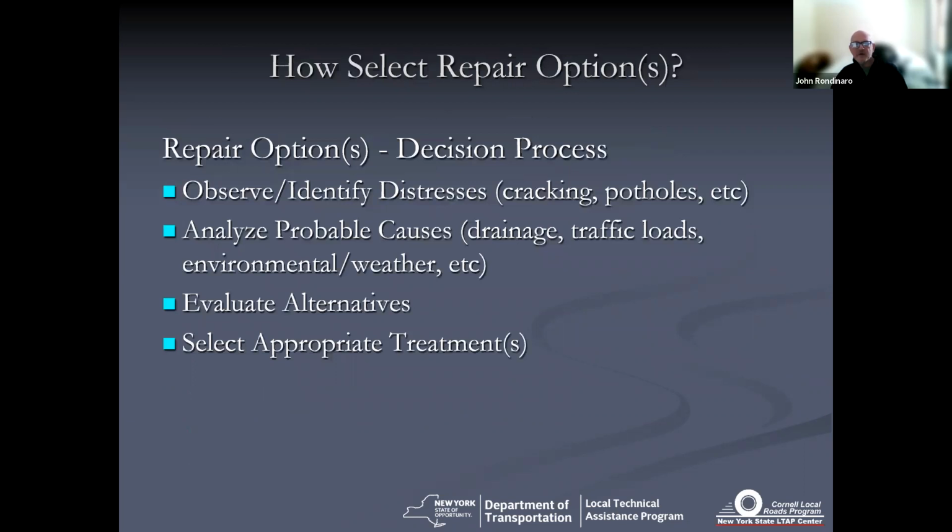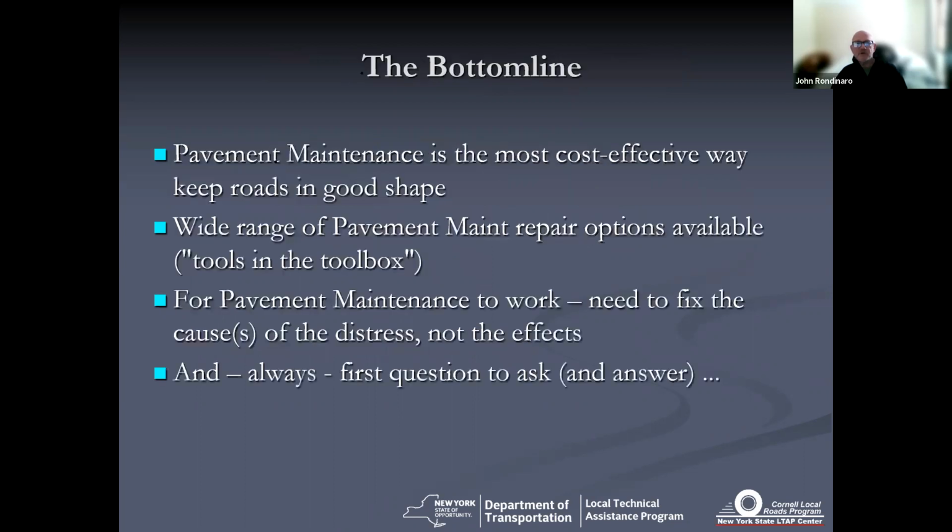And the approach to pick our repair options: you're going to be identifying your distresses, rating your distresses, analyzing your probable causes, drainage, traffic, environmental. You're going to evaluate your appropriate alternatives, and you're going to recommend a treatment or two to tackle your problems.